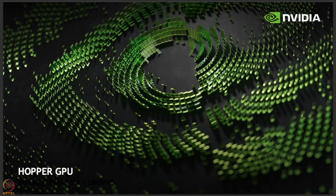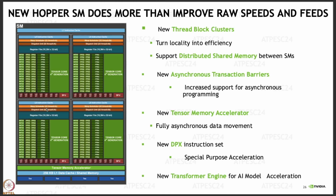Let us now look at the Hopper GPU. So the Hopper is a new symmetric multiprocessor which improves raw speeds and feeds. It has ideas like new thread block clusters which turn locality into efficiency. We will discuss these advanced topics in future lectures of GPU. It also supports distributed shared memory between symmetric multiprocessors. It has a new tensor memory accelerator and supports fully asynchronous data movement. And it has special new instruction sets called DPX and a new transformer engine for AI modeling and acceleration.